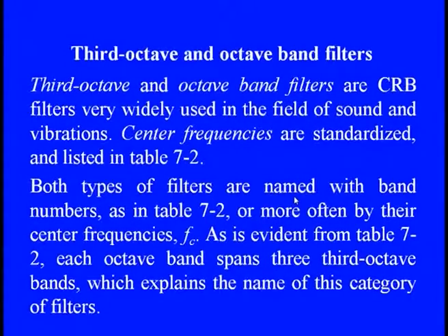When we are talking about the third octave or octave band filter, they are nothing but constant relative bandwidth filters, and they are widely used in vibration analysis, in which the main part is the central frequency, which needs to be standardized, and then we can simply configure the other two. Both types of filters are named with the band number, as I am going to show you in the table, and more often by their central frequencies, which can be varied accordingly.